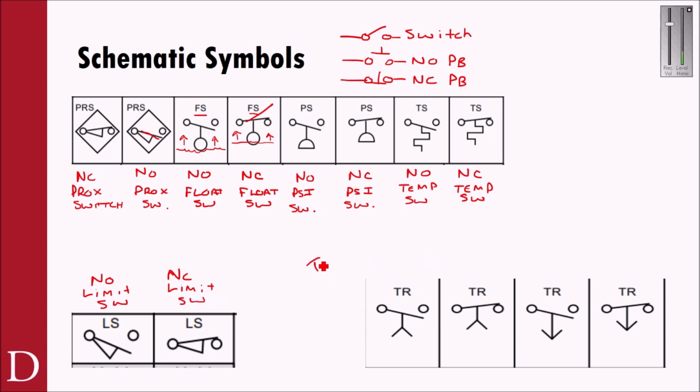And now these are some of the timing contacts. You'll have to remember back, but we used some timing relays in this lab. I'll designate these with the acronyms, but pay attention to what I write here. You can see this is normally open, and you'll see the direction of the arrow. This is normally open, timed to close, NOTC. It's drawn normally open, and the action is going to be in the closing direction, as signified by that arrow.